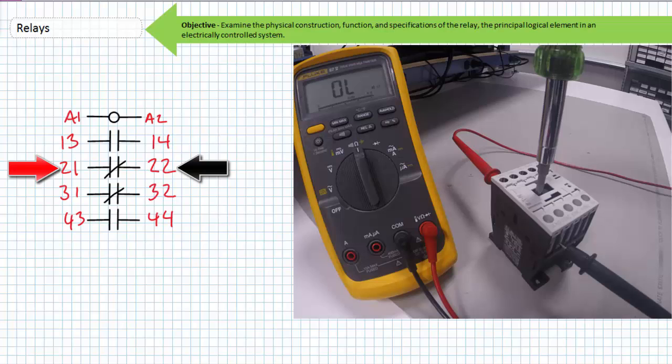Similar to their big brother, the contactor, mini contactor relays sometimes feature an access port on the side to allow a mechanical interlock between two relays in close physical proximity. The mechanical interlock may be as simple as a plastic peg or as complicated as a separate interlock unit that prevents the travel of one relay's contact carrier if the one it is mechanically interlocked to is already energized. This can prevent two mutually exclusive conditions from occurring inside an electrically controlled system's logic.